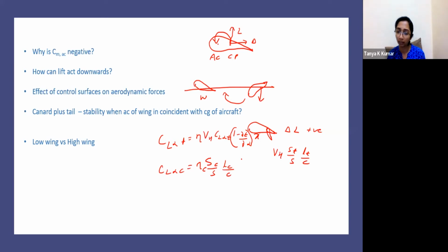The downwash component acts on the tail due to the after effects of the airflow over the wing. There will be no downwash effect on the canard. If we ignore the downwash effects on the tail, then these two terms, if all other geometric parameters are the same, may cancel out.